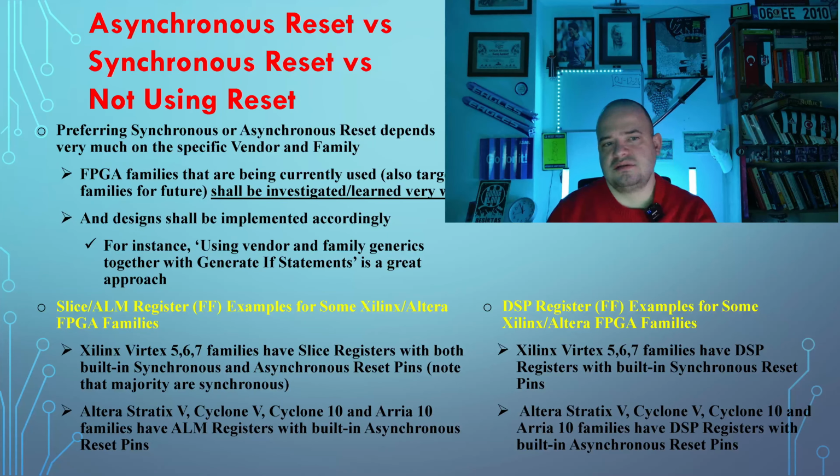As I mentioned, preferring a synchronous or asynchronous one depends very much on the specific vendor and family. There are some nice good examples here. In terms of slices or flip-flops, Xilinx calls those slices, Altera calls these ALMs, adaptive logic modules. I provided some slice/ALM register examples for some Xilinx and Altera FPGA families.